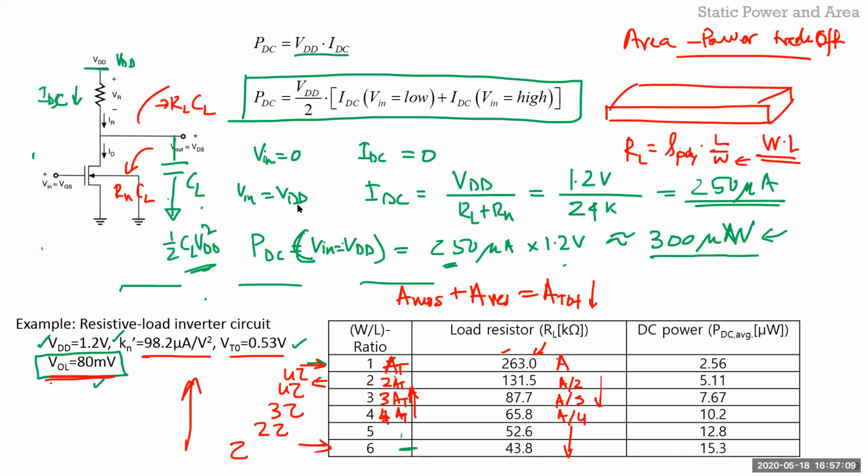Sir, resistor is rho L by A, and here it is rho L by W. The resistor and NMOS are both in series, right? So my W by L means L1 plus L2, both the lengths will be added. That means it will get doubled if both have the same length. So my resistor value should be increased because it is L by W.